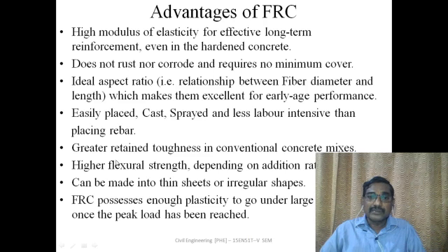The most important advantages of fiber reinforced concrete are they are having high flexural strength, highly resistant to water, fire, atmosphere, ideal aspect ratio, that is relationship between fiber diameter and fiber length, which makes them excellent for early age performance. Easily placed, cast, sprayed, and less labor is required for working.